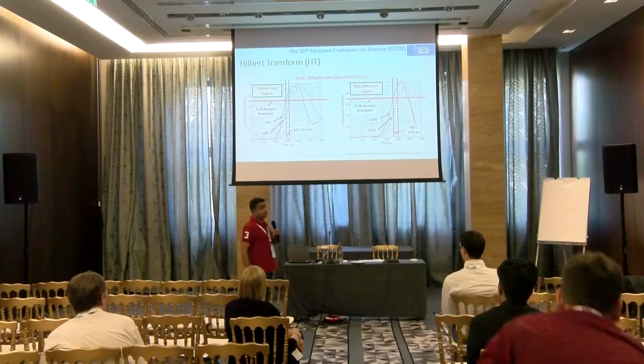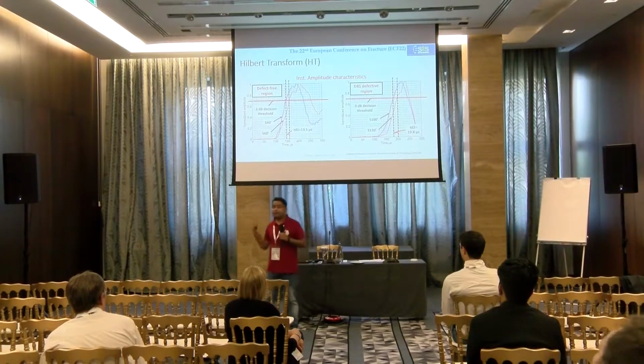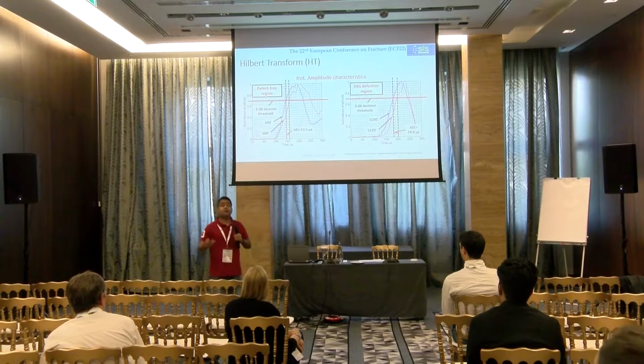So we have the fixed distance 20 mm and we have the time interval, so we can find the velocity of ultrasound wave in defect-free region and defective region as well.